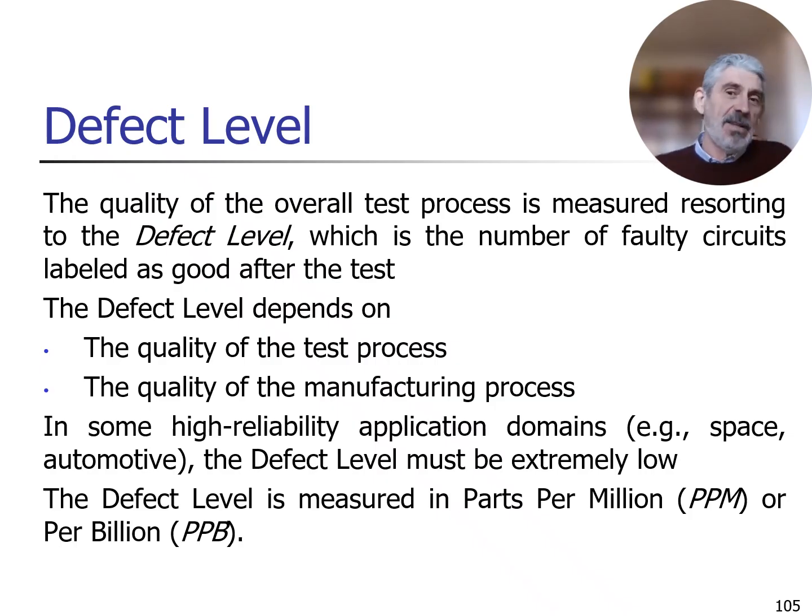On the other side, if the manufacturing process is extremely immature, meaning that a lot of faulty products are manufactured, the test process should be very selective, very high quality, in order to guarantee that only a limited defect level is produced.